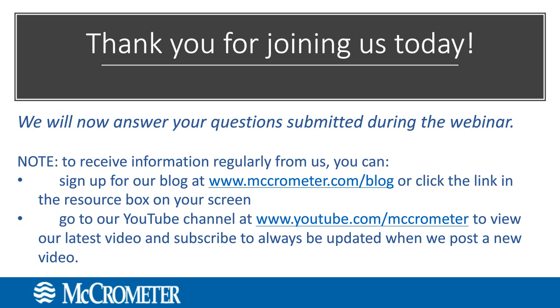Okay, thank you. The next question is, can you mount a DP transmitter directly on the meter? So yes, one option I didn't really show off in here, however we do have, is for direct mount, we would call it. We're able to put a direct mount plate on top of the set of taps. So for the various transmitters that are configured for that, we're able to do so.